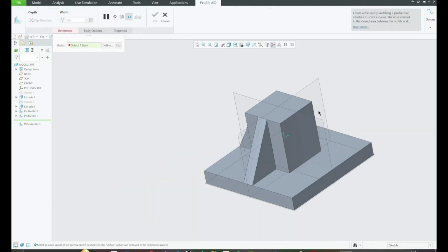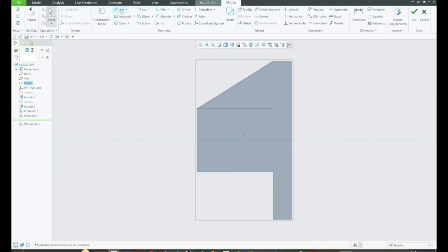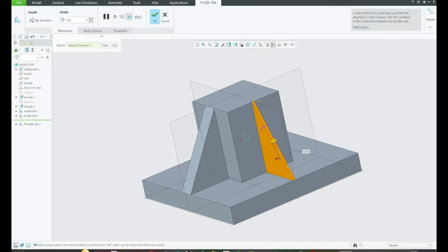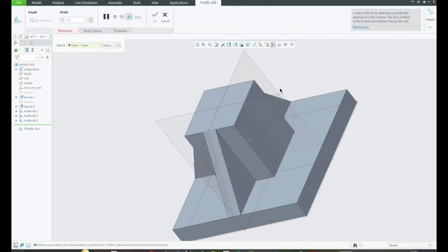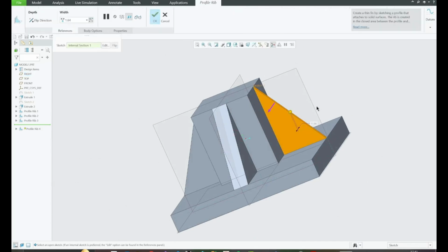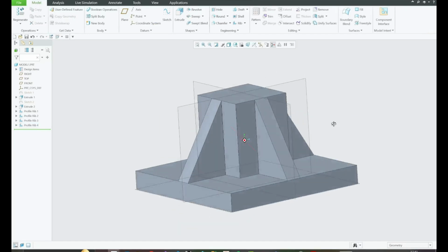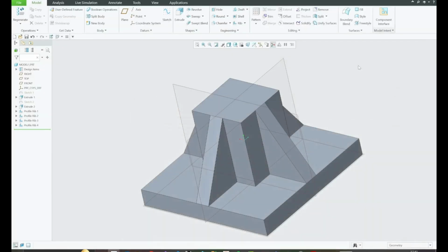Similar thing over here as well. Click here, press the sketch view, and then make a line from this point to this one. Press escape. We've got our rib profile ready. Press OK and change it to 10, and OK. Do it again over here, and we're gonna make a line from here to here. Press escape. We've got a rib profile, and change it to 10 as well. Press OK. Perfect. So now you can see we've got our model ready, this one from this drawing.